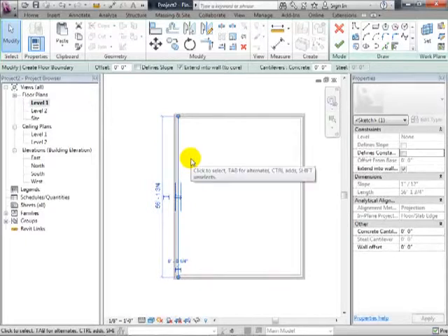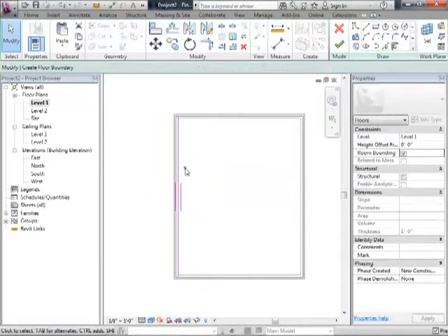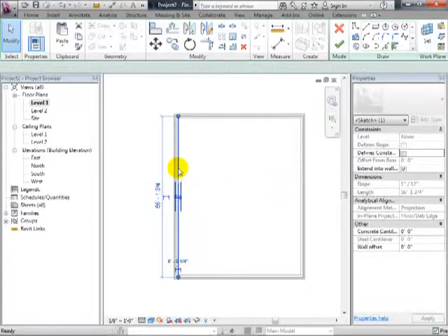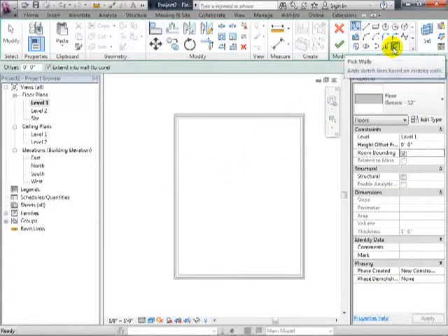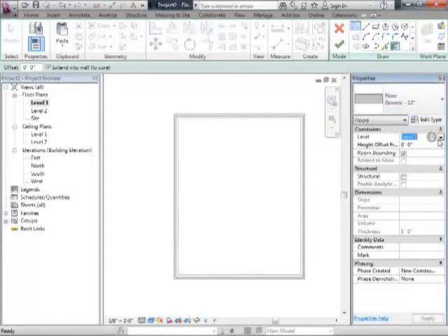I'm putting the floor at level 1. What I really want to do is put the floor at level 2, so it would be halfway up the wall as opposed to right down in the middle. Let me fix that. I'm sorry, I wasn't paying attention. I'm going to choose the floor tool, and instead of putting it at level 1, I'll put it up at level 2. That way it's going to intersect with the wall as opposed to just being underneath the bottom of the wall.